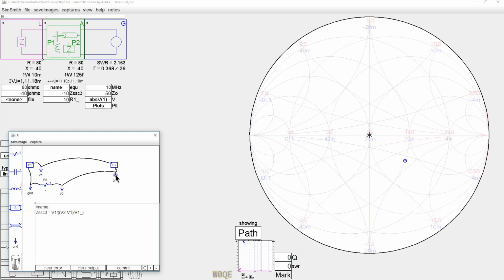However, what we've done here is we've just shorted out this resistor. We really need to remove this ground right there. And if we do that, this circuit will work correctly too. Now, the voltage is V1. The current is V2 over R1, not V2 minus V1, which is good. And we wanted that. That was the thing we were trying to get rid of.